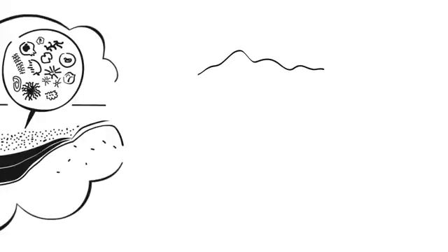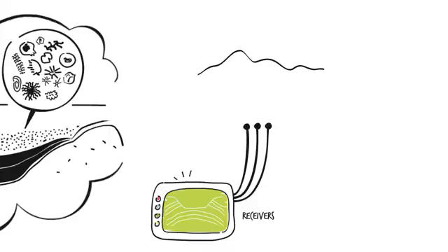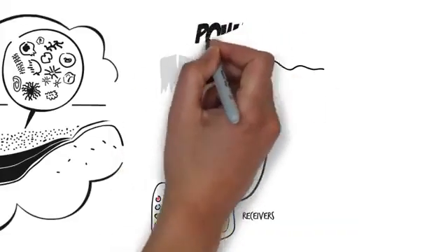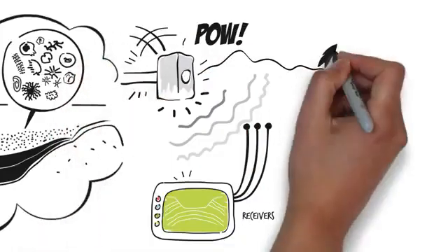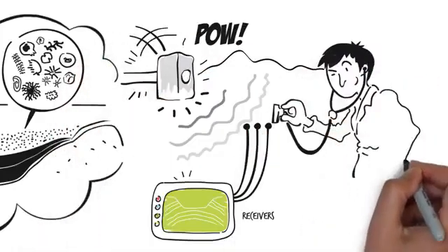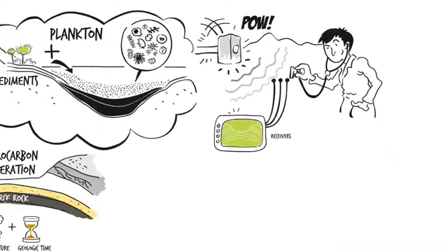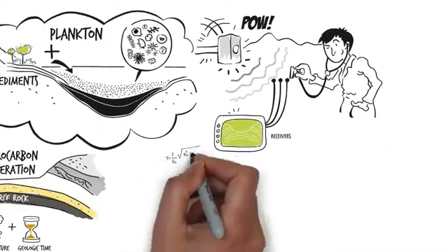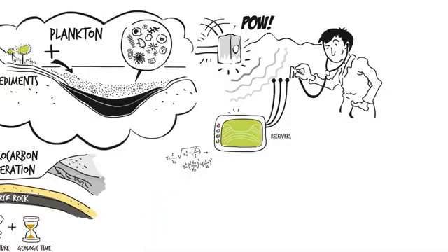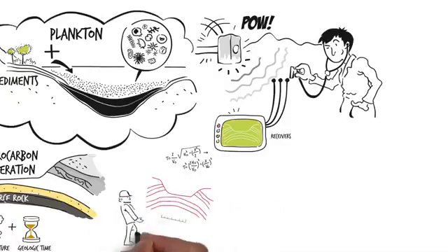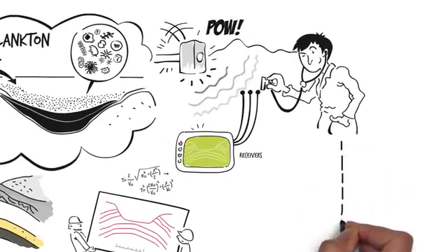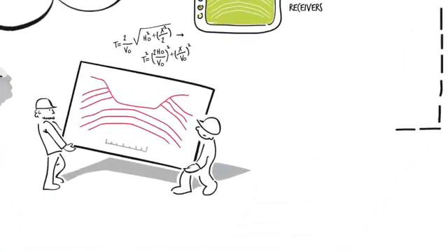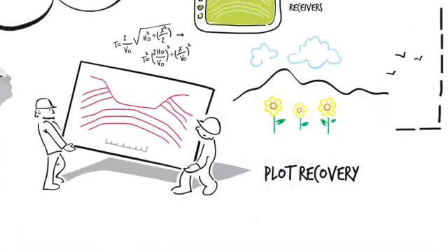The area to be surveyed is mapped out. Receivers are set up to record the seismic waves on the surface. A survey is carried out using acoustic waves, and the time which elapses between the emission of the sound waves and their return is measured. The data is stored in digital format for further mathematical processing, and in this way, a spatially corrected image of the strata is obtained, illuminating any subsurface geometries or traps. Once these tasks are completed, the land is restored to its original condition.